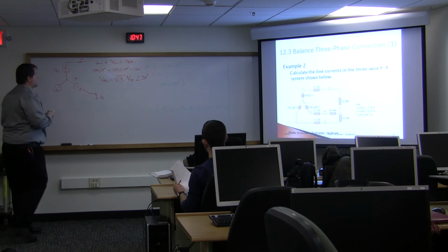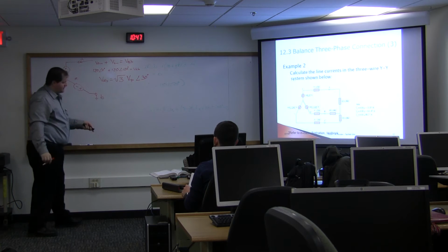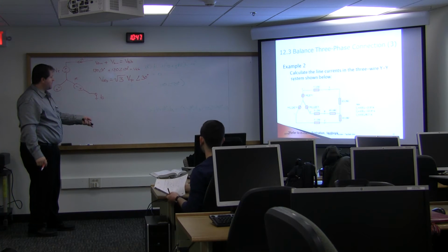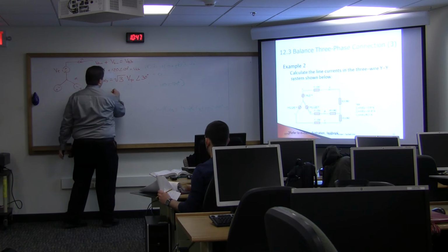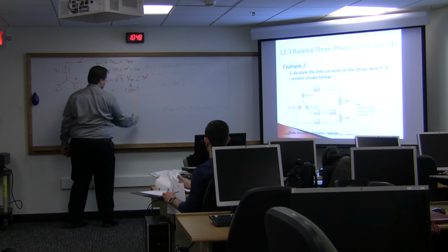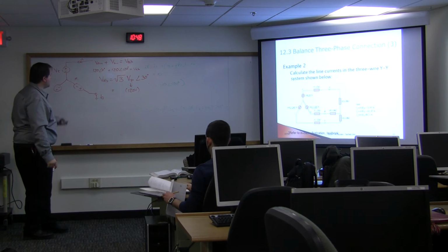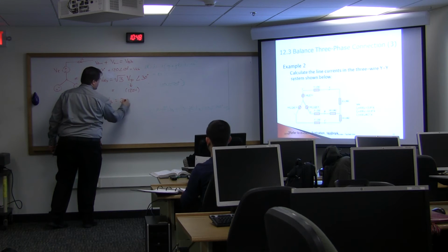And the one reason I wanted to point this out was just that oftentimes we understand our phase voltage, the voltage on a single phase coming out, is like 120 volts. But when you deal with three phase, oftentimes it's quoted as 208.